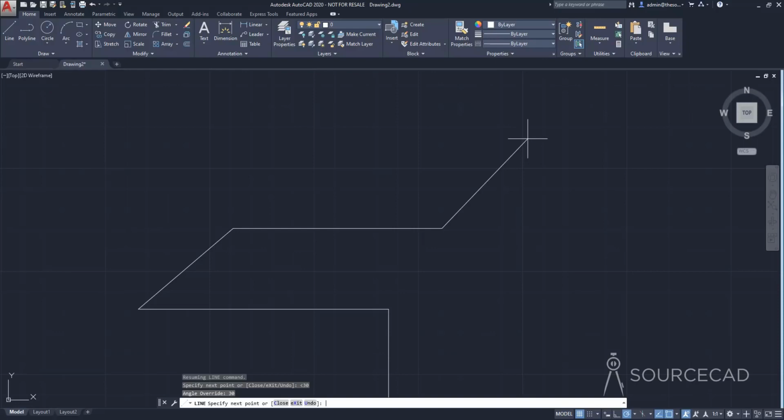and AutoCAD will now take this value as angle, not as distance. So if you move your cursor now, you're going to see angle override here, which is now set to 30. So if you now move your cursor, the length will change here, but not the angle. So all you need to do is now type in the length. So maybe I'll type 50, enter, and here it is. So now the length of this line is 50, and it is inclined at an angle of 30 degrees with respect to the positive side of the x-axis.